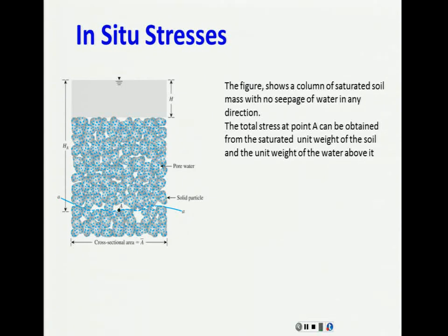That's basically it. All the pressure that is applied at that point is coming from the pressure that the soil is acting onto that point, as well as the water. So we have two parts that are going to conform that one. The first part is this height of water, only the column of the water here, multiplied by the unit weight of the water.